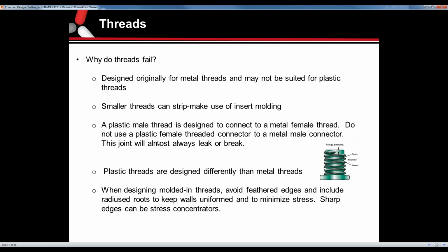Overmolded inserts. Yeah, exactly. When you get down to the smaller sizes, anything from a 1/4 down and smaller, it's always an option to either do molded-in inserts or even do heat staking and so forth to get those threads in the part for you. Correct.